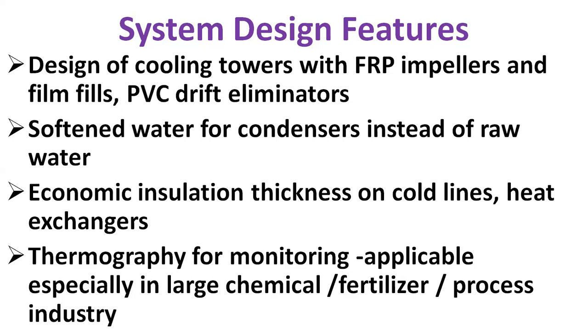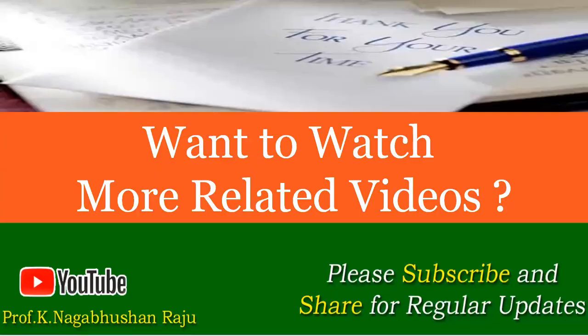And finally, adopting variable air volume systems, sun film application for heat reflection, optimizing lighting loads in the air-conditioned areas, and optimizing the number of air changes in the air conditioning areas are a few other examples which need to be considered in the system design features.